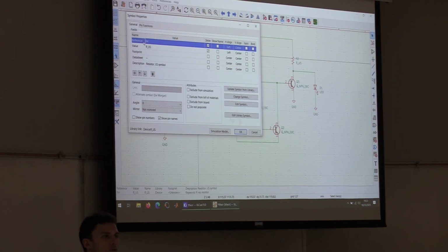Now's a great time to explain what a reference designator is too. A reference designator allows us to understand which part is where, and it's a unique way of identifying a part within a PCB. So if you ever open up any piece of electronics and look at the circuit board, you'll see beside every single component there's a little letter, usually followed by a number.